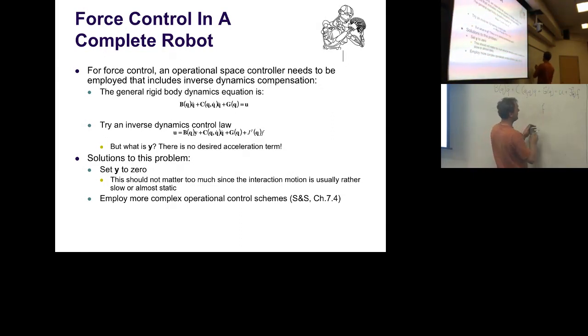So this is exactly the control law which we had, just this super simple F equals, I think it was, m times x double dot minus x dot plus kp over ke times ef plus f desired. So this is the F you plug in there. It's in end effector space since we're touching the world with the end effector.